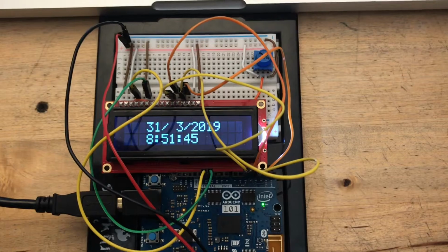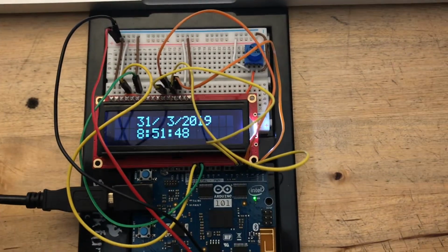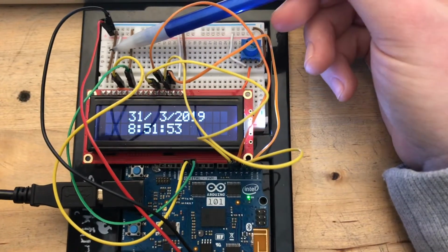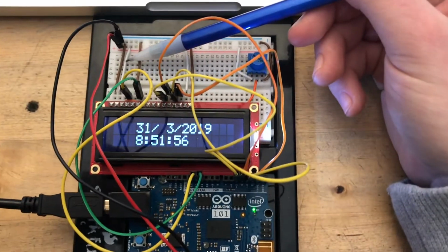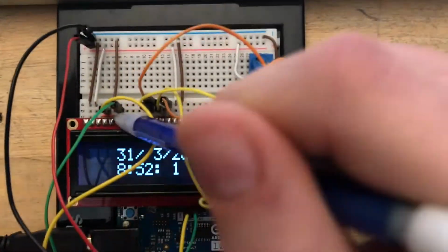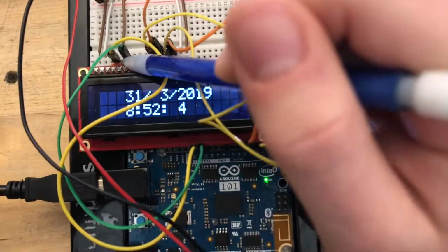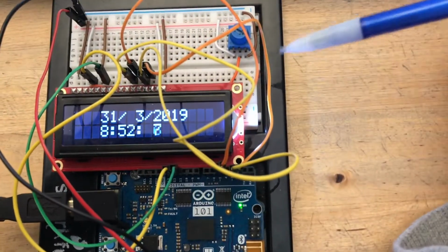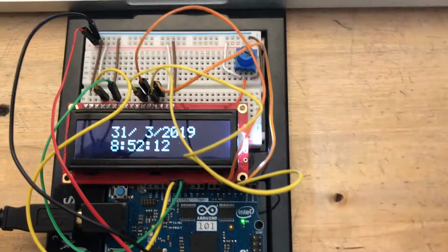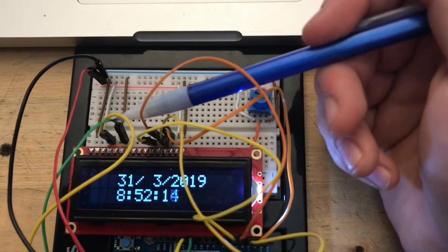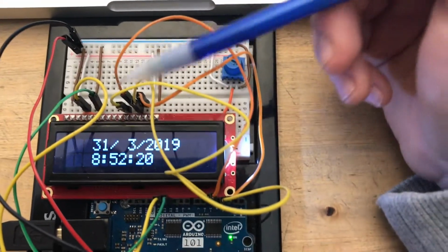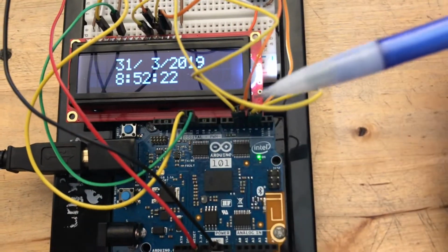Here's the basic board for using the onboard time clock. Here we have the LCD screen wired in the same way as the LCD tutorial, but we can explain it again. Here it is grounded by this brown wire here. It's connected to the 3.3 volts through this white wire and then through the red wire. The next pin here is going to be this orange cable here, which is the LCD operation voltage test pin, and that's going to connect to this potentiometer that controls the contrast of the board. The next wire here is this yellow wire. It is the data and control register select input. That's going to be connected to pin number 12 on the Arduino board.